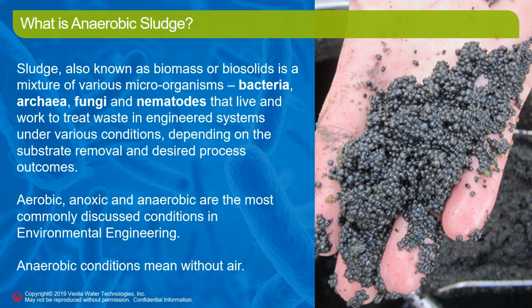And we're going to try and reduce the amount of waste in the wastewater system. So like reduce the amount of COD, or in a solids digester, you're going to want to reduce the amount of solids. You're actually going to eat the solids, convert them to something soluble, and then convert that to biogas. Now, these bacteria come in a number of bacteria and fungi and archaea.